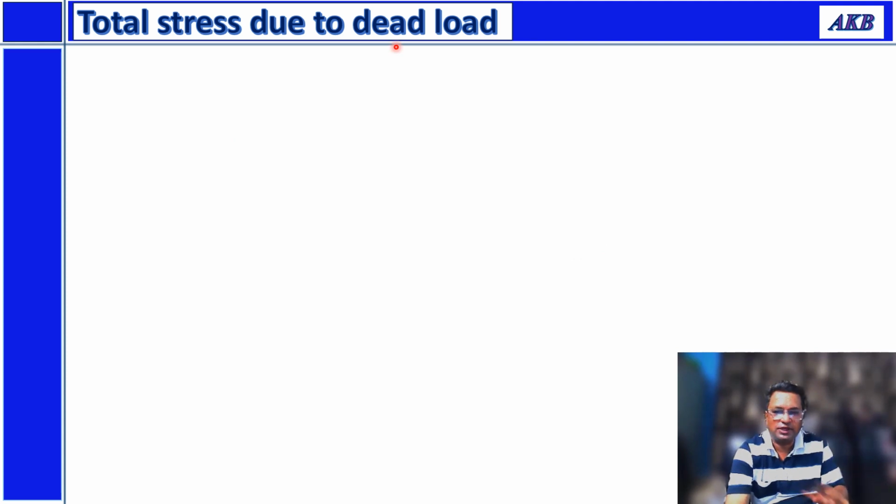Okay, so with this we have covered all the dead loads that are associated with a typical tray column. So we considered weight of the shell, we considered weight of the insulation, then weight of the liquid, then we also considered weight of various attachments. Okay, so let us summarize that. So various stresses induced due to various dead loads.